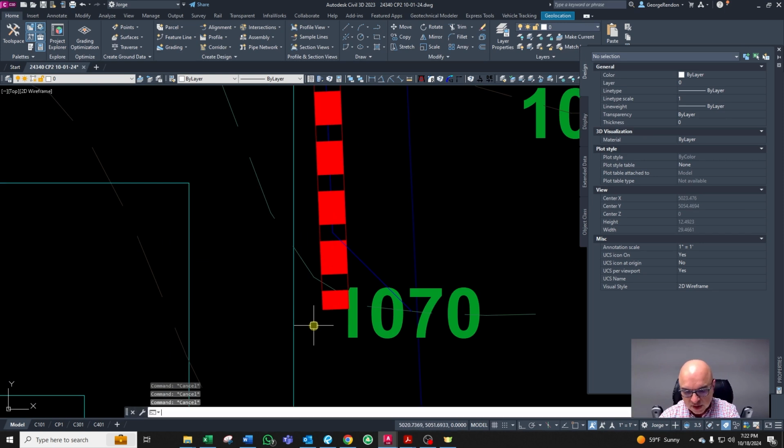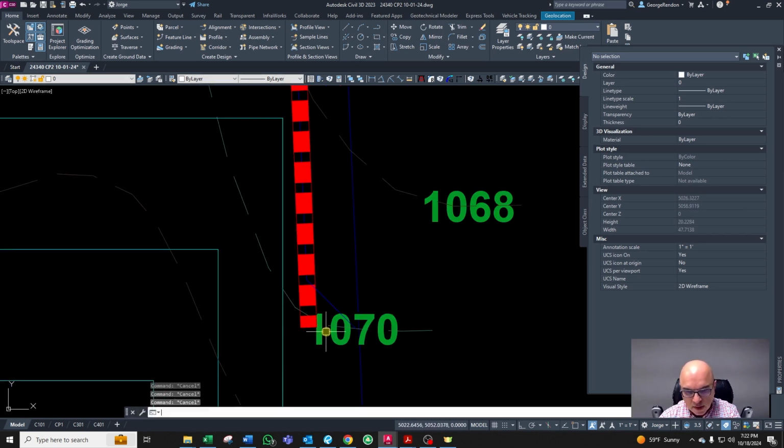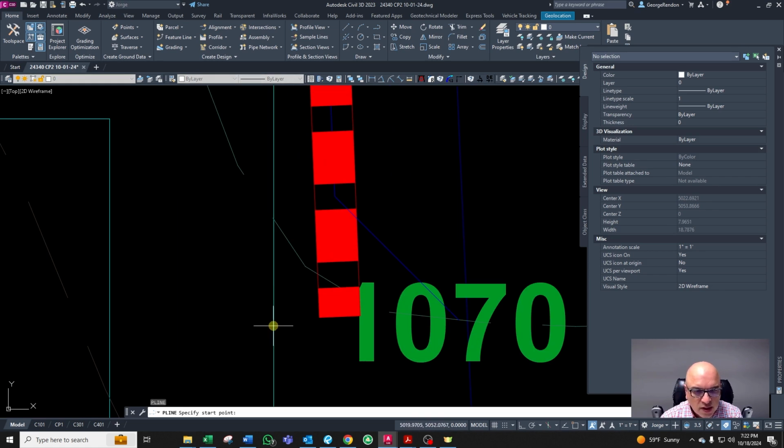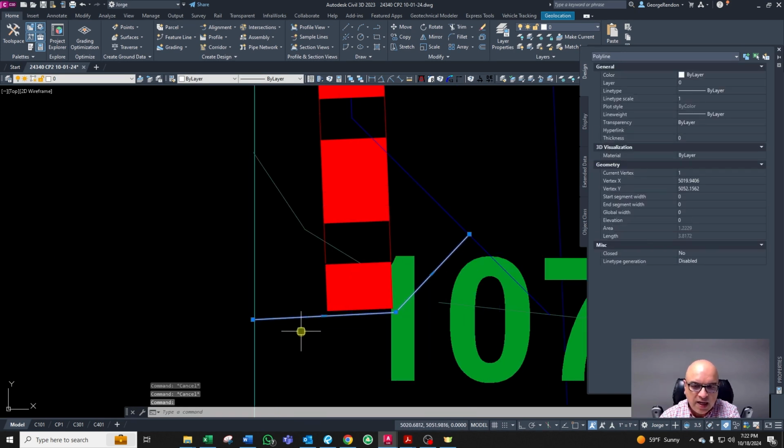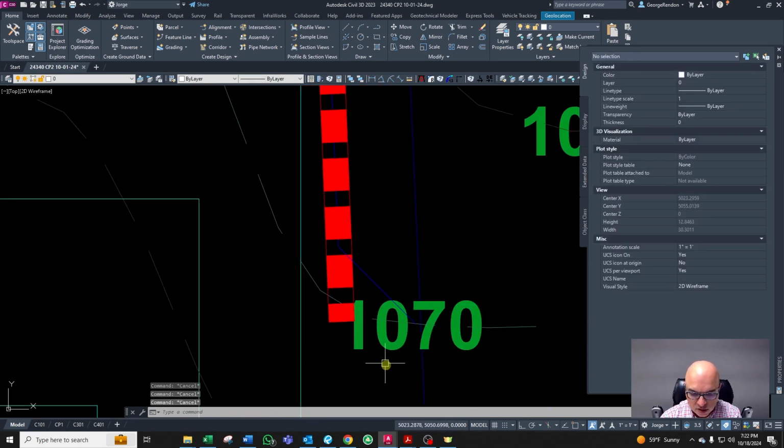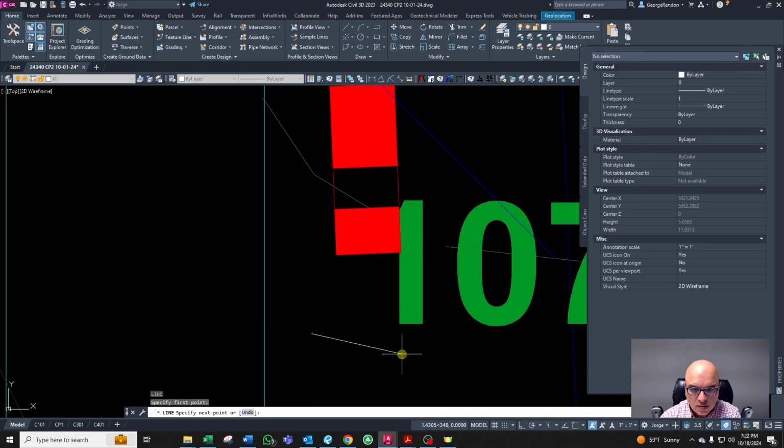So you can have a 2 to 1 slope coming down and coming down. But actually the right way to do it is you come down and then perpendicular to this line. We need to be 4 feet. We're almost there. So the wall needs to be a little bit longer until you provide 4 feet.